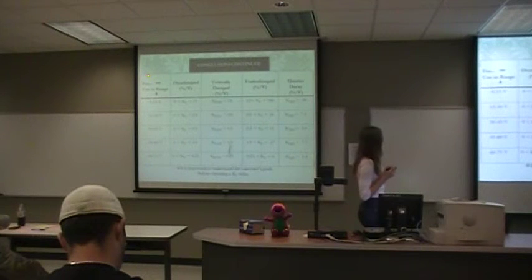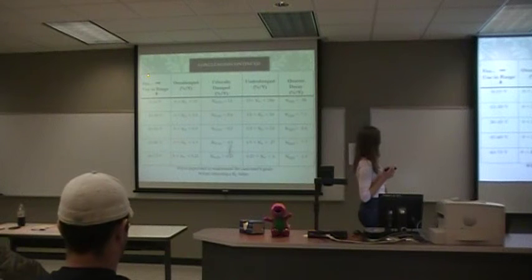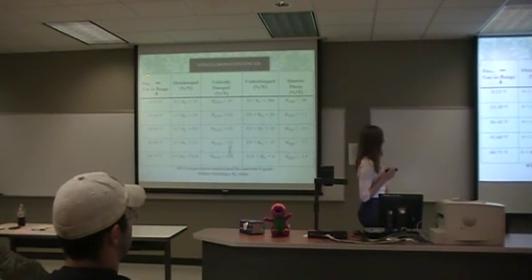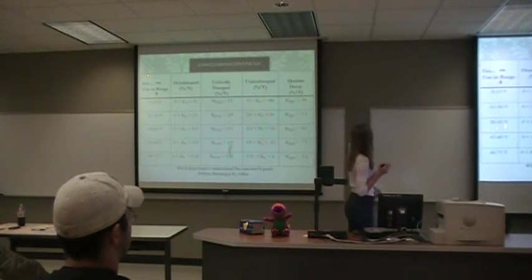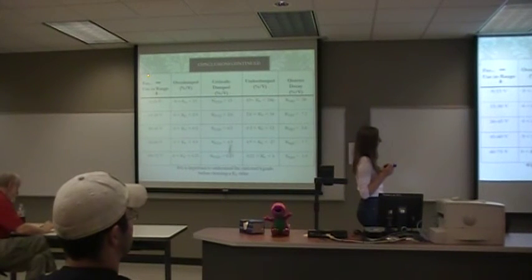For 15 to 30 volts, you're going to use a Kc from 0 to 0.26 for overdamped. Critical damping, you're going to want it to equal 2.6. 2.6 to 34 is your underdamped region, and your quarter decay will be 7.2. For 30 to 45 volts, you're going to have 0 to 0.2 for overdamped. Critical damping is going to equal 0.2, and then 0.2 to 12 is your underdamped Kc value range. For quarter decay, you're going to use 2.6.